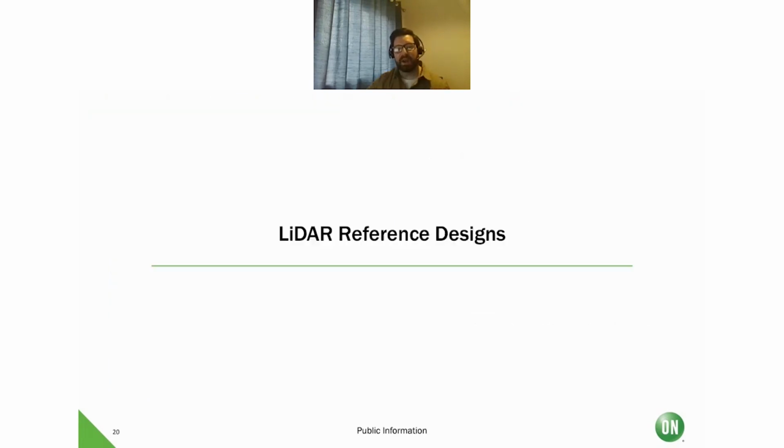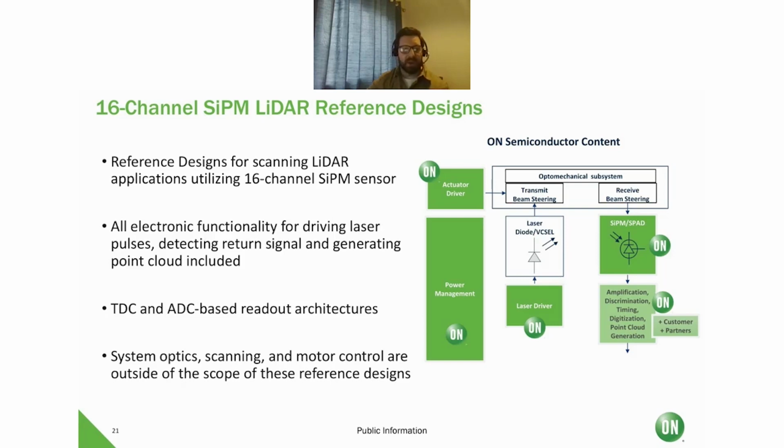So I'd like to talk to you about our LiDAR reference designs. Using this 16-channel SiPM array, we can now offer you both TDC and ADC-based readout architectures. These reference designs are using our 16-channel SiPM for scanning LiDAR applications. They contain all the electronic functionality for driving the laser pulses, detecting the return signals, and generating the point clouds. Just to note that the system optics, scanning, and motor control are outside the scope of these reference designs.